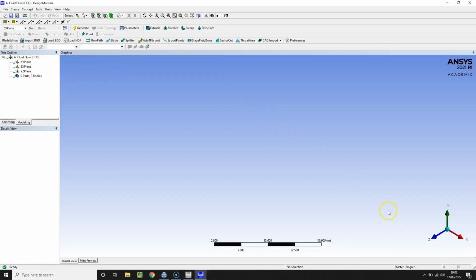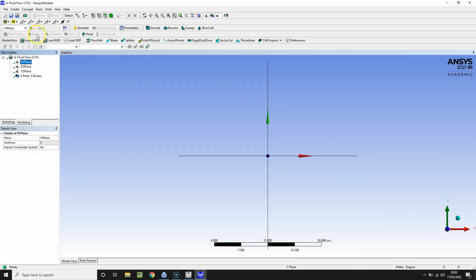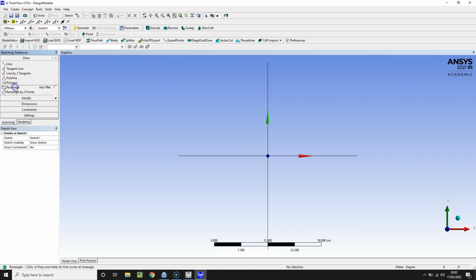And once that's loaded up, we're just going to create the outline of a room by selecting the XY plane and creating a new sketch beginning at the origin. So just approximate the shape of a rectangular room by making sure the cursor has that point logo, and then expand out to approximate the size of a domestic room. So here that's probably more than large enough.